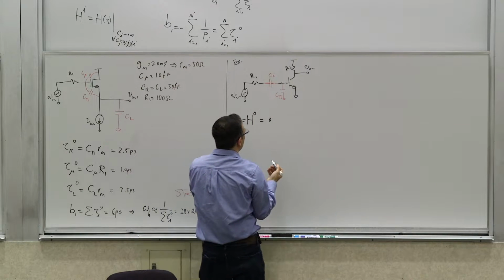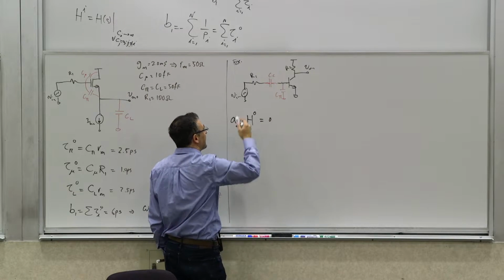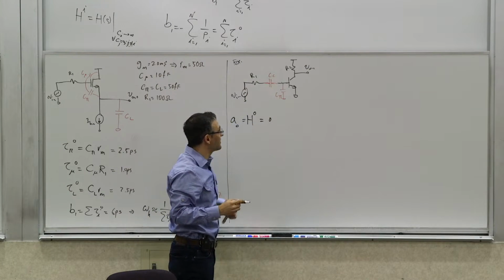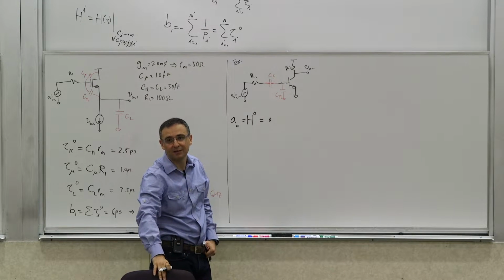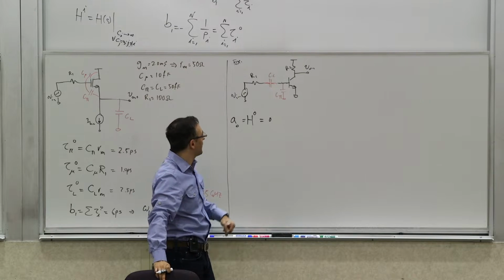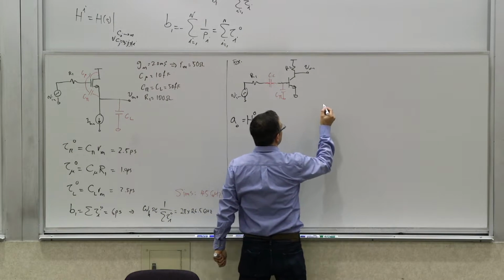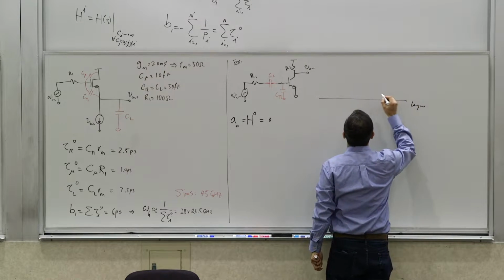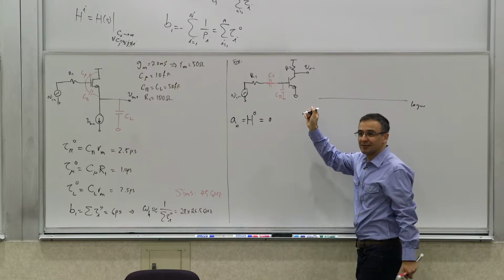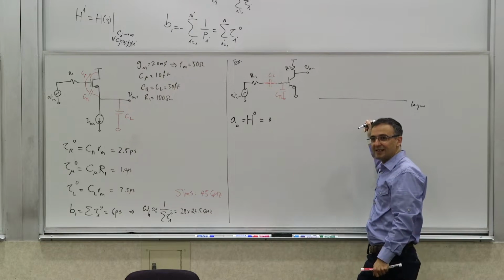And so what does the transfer function look like for something like this, and what is the gain at infinity? I mean, if I short circuit all capacitors and open circuit all inductors, it's 0 again, because now this guy is going to be 0. So I know I have a circuit, so how would the transfer function look? If it's log of omega, I know at DC its gain is 0. At infinity, its gain is 0.